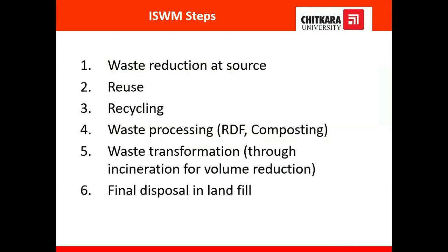Integrated solid waste management steps. Most of the developed countries use this technology so that wealth can be derived to the maximum extent from the waste materials. It starts with waste reduction at the source, then reuse, recycling, waste processing using RDF and composting, and waste transformation through incineration for volume reduction. The volume of waste is very huge, so it can be reduced by incineration, and that will give energy as a byproduct that can be used further. Then final disposal into the landfill site.